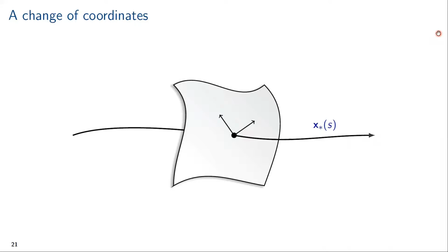This brings us back to this figure, which we saw earlier in the talk. We assume now that we have already found some sort of nominal trajectory parameterized in terms of S. So we have solved this trajectory optimization problem, and it has given us some desired trajectory which we are satisfied with. Now we want to use this to design an orbitally stabilizing feedback controller. Again, the plan is, given some state, we can recover the corresponding value of S. That is, we can project down upon the nominal orbit, then we can get some measure of distance to it.